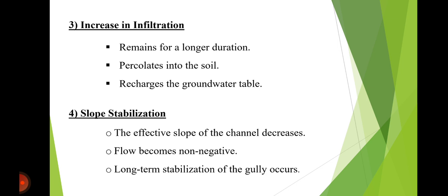Slope stabilization of the gully bed. The sediment accumulated behind the check dam gradually raises the gully bed. This reduces the effective slope and helps prevent further deepening of the gully. So this is the stabilization of the gully bed.